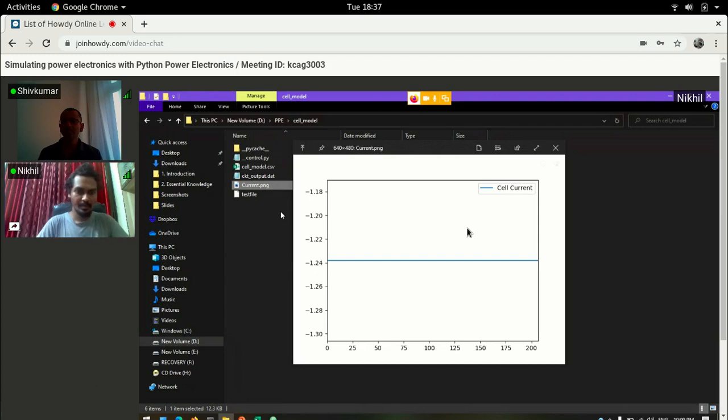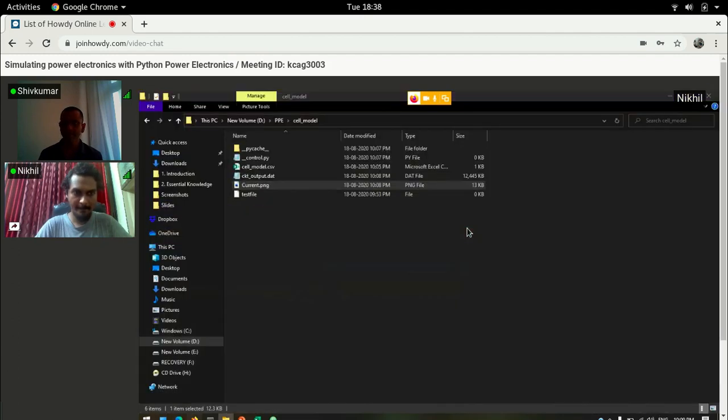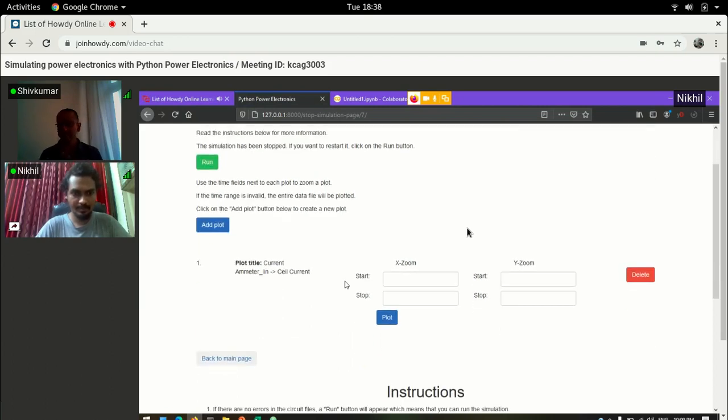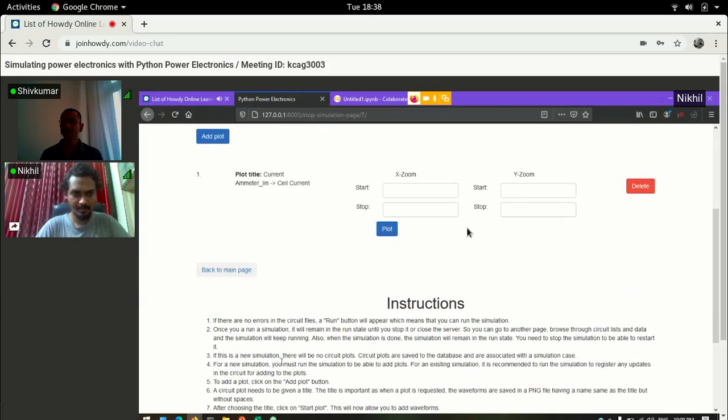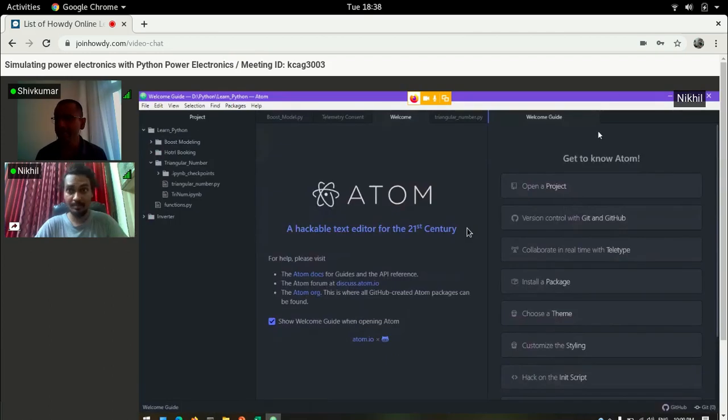So now that this is done, we can stop the simulation. We can now start writing some control. The first thing I would say is, let us now integrate this current, right, and try to see what the charge looks like. So let's say, for example, we do 1 by C integral I dt.